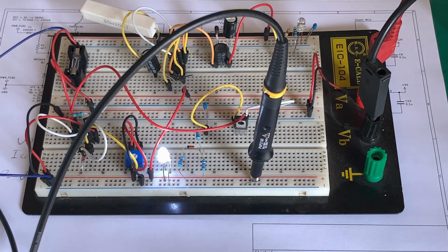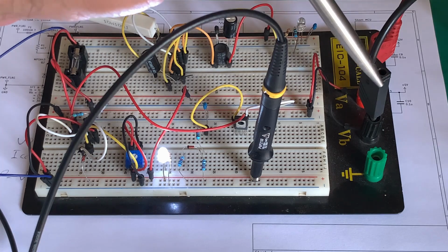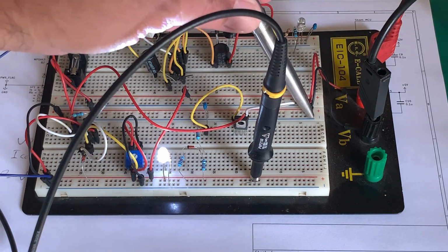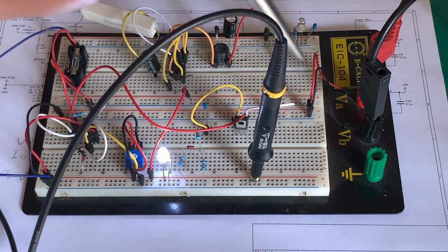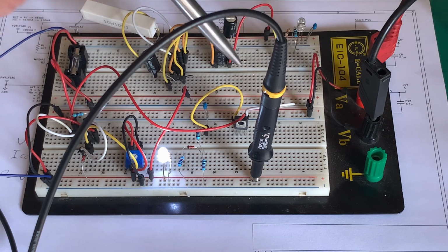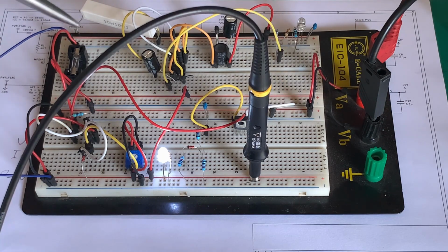So here is our breadboarded circuit. Don't worry too much about what's going on up here. That's the switching regulator that we're not discussing today. But basically our DC voltage from our bench power supply comes onto that rail over here, currently sitting at 56 volts. We take that rail, we go through a fuse, and we come down to here.